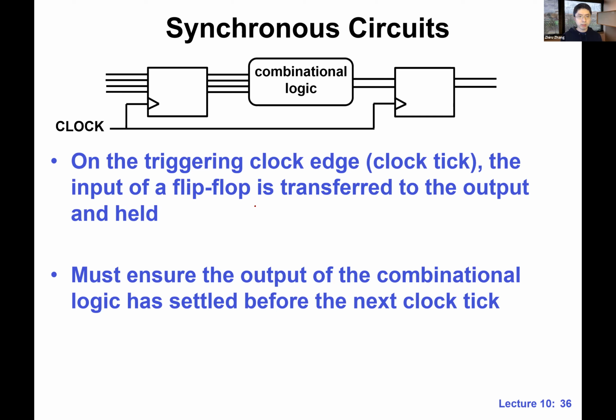But we only capture the states, we only update the states of our system at the clock edge, using the flip-flops. So that's why it's called synchronous. And this is the precise reason that we want to use the flip-flop, because we want to avoid the implication of the glitches.